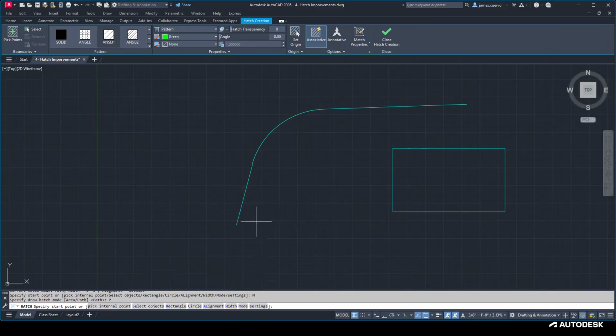Hypothetically, we want to set up an area here that is, let's say, 5 feet, and it's going to be a no parking area, just to give it some sort of utility. In order to do that, we first set up the width. By default, and I have been playing with this a little bit, it's set to 2 feet. We said we wanted 5 feet, so we set the width of this path that we're going to hatch to be 5 feet.